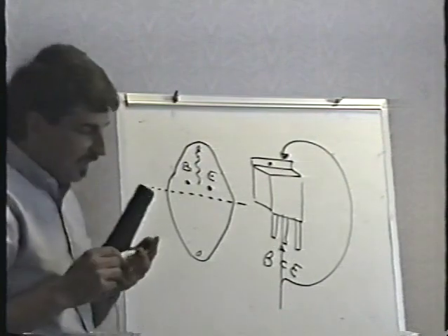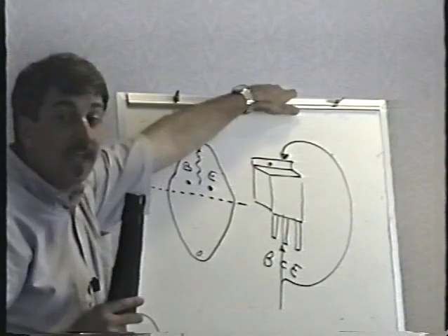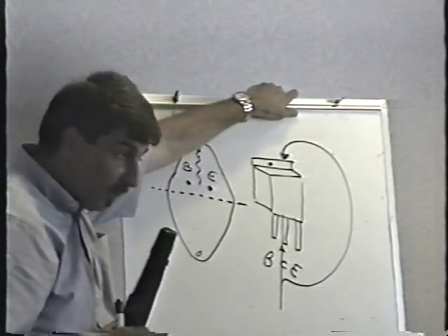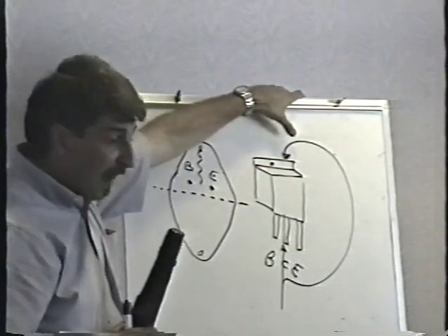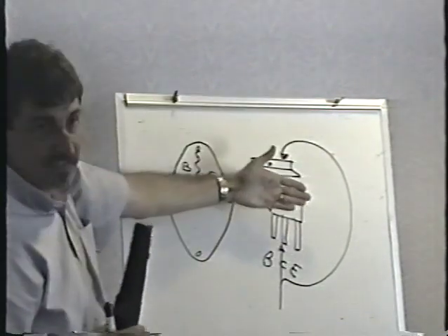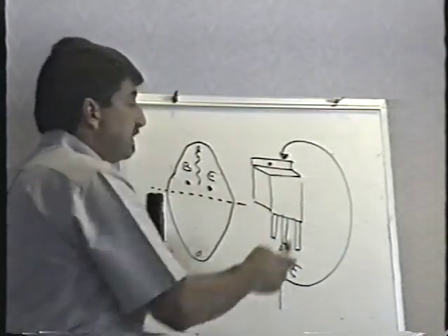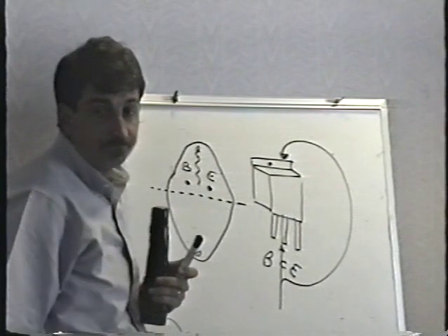These are electrically the same point, meaning that the metal tab is electrically active. It is the collector as well. And again, when we open up our power supplies, you'll see that there's an insulator behind these things as well. There's a small insulator that goes behind these transistors as well.